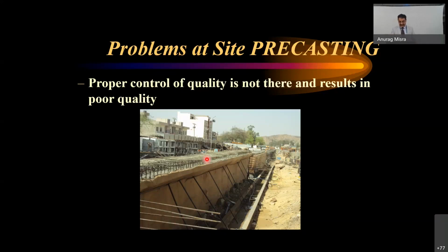But you can imagine how effective the curing will be. Even if they are taking good precautions, uniform and very effective curing is not going to be possible that way. Either we go for a sprinkler system, which is a very good way, but that would involve lots of investment and wastage of water as well.